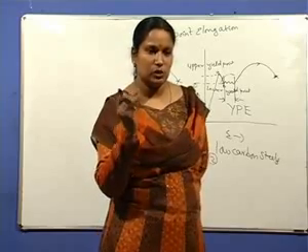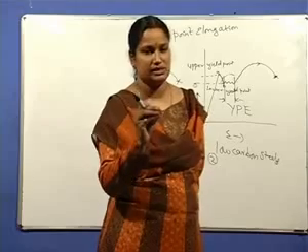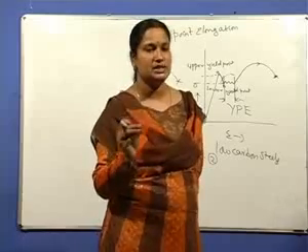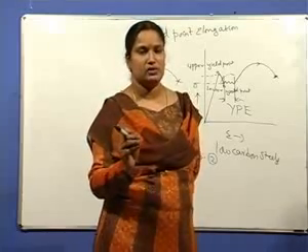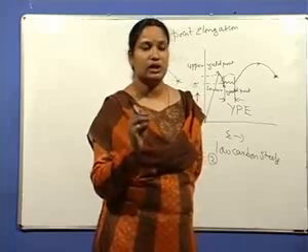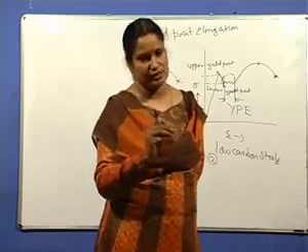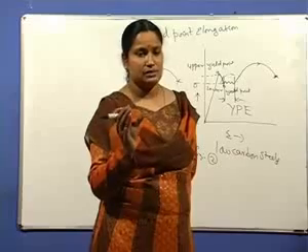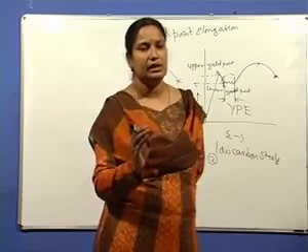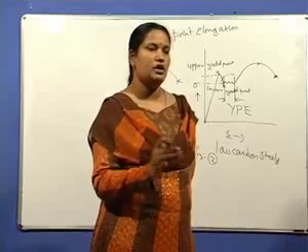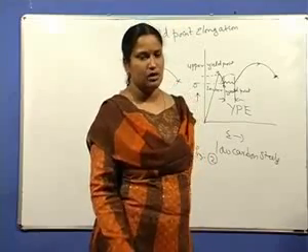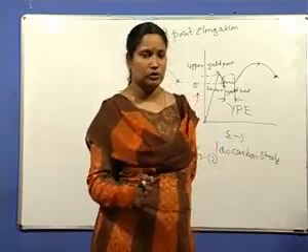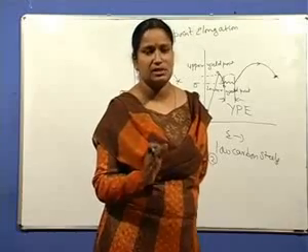Or the solute atoms go into the interstitial sites if their size is much smaller. Interstitial elements like carbon, boron, hydrogen and nitrogen go into the interstitial sites because of their very small size, so they form interstitial solid solutions. Whereas solute atoms which have nearly the same size as the solvent atom form substitutional solid solutions. Whether substitutional or interstitial, both strain the crystal lattice.